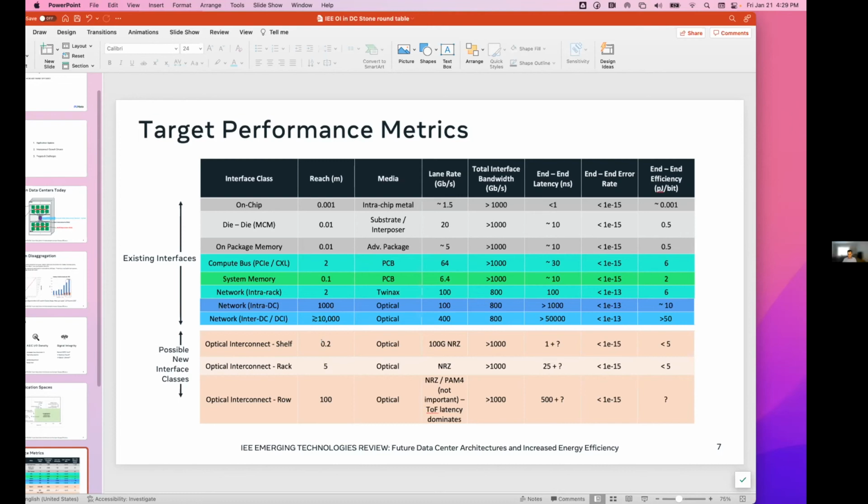Publicly they've stated in multiple forums they're doubling everything every 2 years, so they're going to be 100 gigabit per second this year. PCIe is so outdated. Forget about it. When it comes to AI scale, AI interconnect cannot live on PCIe. 64 gigabit per second, PAM4 with PCIe Gen 6 at the end of 2025 is just so out of date, so irrelevant to AI.